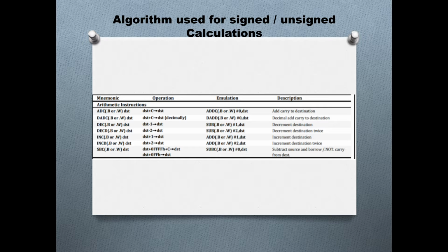Multiplication and division in the absence of a hardware multiplier require many instruction cycles, especially in C. This report discusses a method that does not need a hardware multiplier and can perform multiplication and division with only shift and add instructions. The method described in this application report is based on Horner's method.